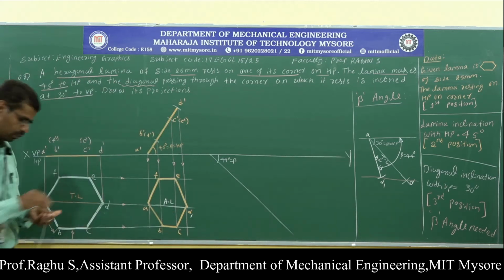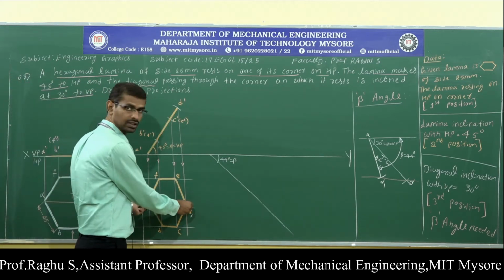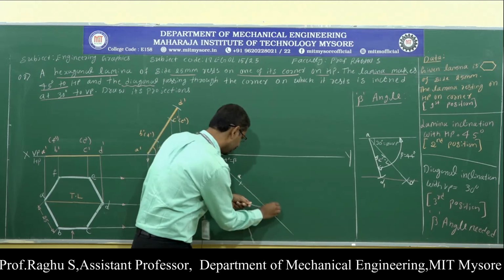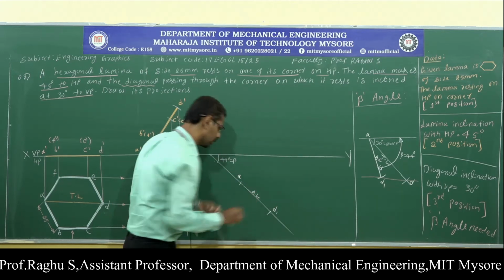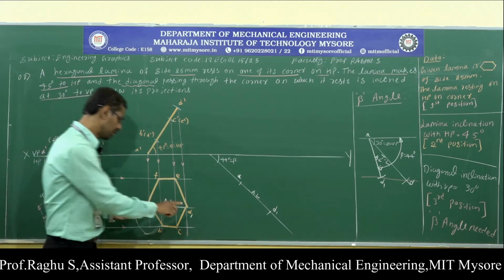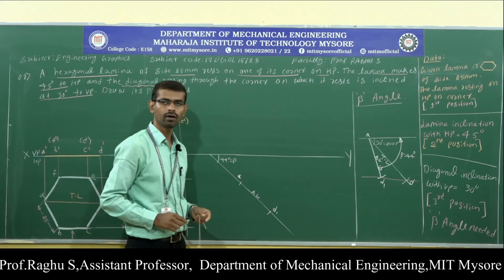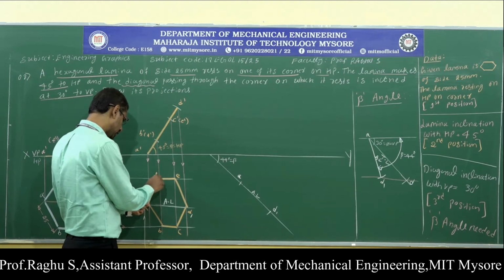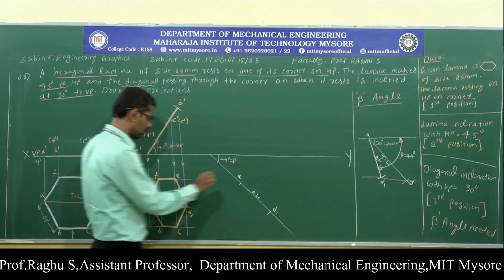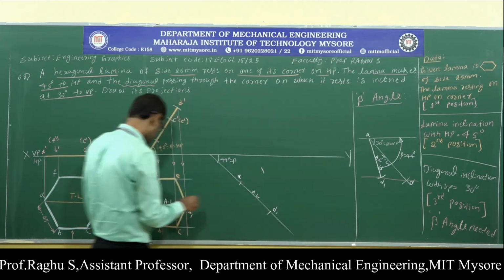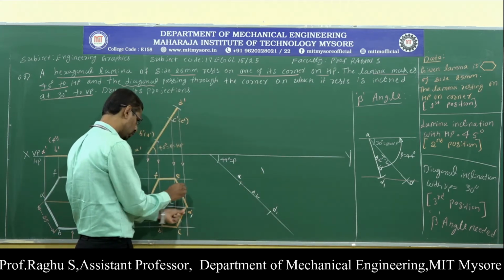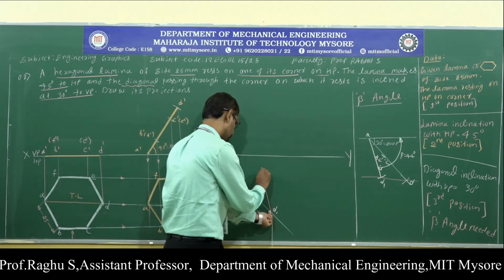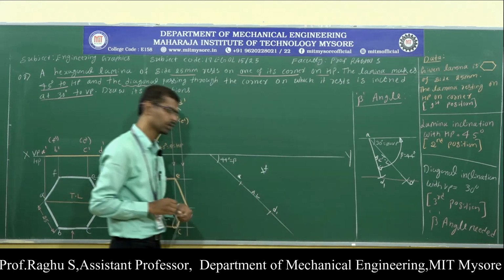For that, first you measure this length AD1. Now fix it on the beta angle line. So AD1 is the apparent length of the diagonal. Next you have to redraw the remaining points. Measure this distance from A to F. I know the position of A, so cut an arc. Then measure the distance from D1 to F, cut an arc to get point F, right?